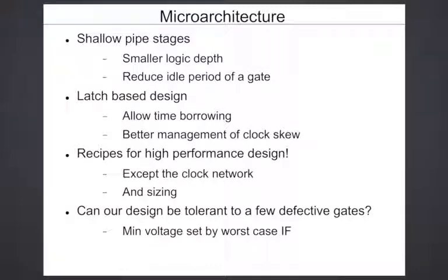But the same cannot be said for logic. For now, the foundries have done a fantastic job. The yields go up, you don't even worry. A NAND gate fails, it never happens. If a gate fails, you have to throw the chip away because your circuitry is not there to take care of it. But the question is, with sub-threshold, near-threshold computing, with so much variation, can you afford to do the design in the same way? Or do you also, at design time itself, allow for failure of gates? How do you deal with that? Can you bring the concepts of ECC or some coding concepts into your design?